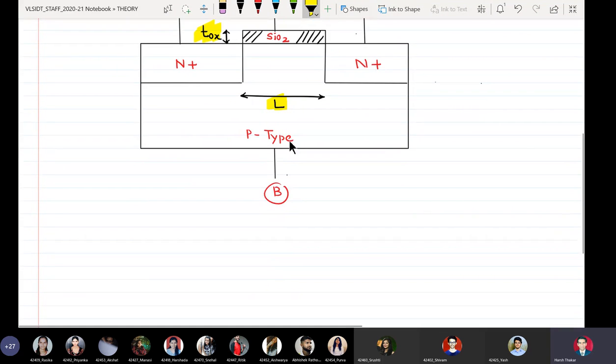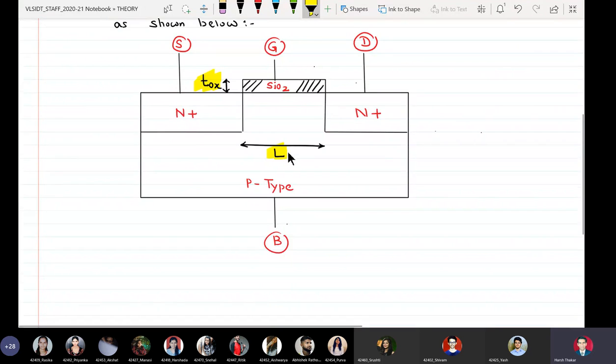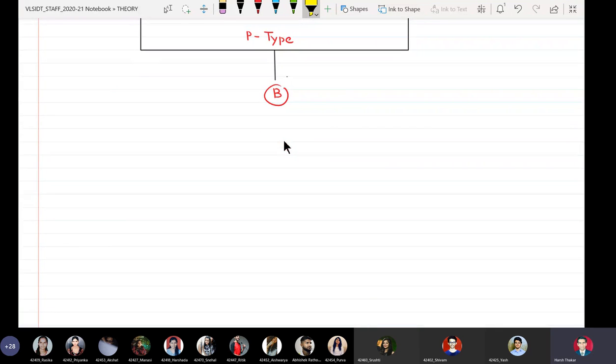Right. So we already discussed a topic called technology scaling, and one of the types of technology scaling is called transistor scaling, while the other is called interconnect scaling. Under transistor scaling, we have constant field scaling, also called Dennard scaling, constant voltage scaling, and we have the lateral shrink, also called lateral scaling or gate shrink. So we already discussed that when the transistor's dimensions are scaled down,